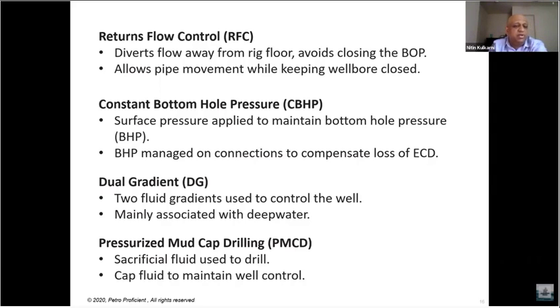In that case, you use sacrificial fluid in the well, which you continue to lose, and then you have a cap fluid in your annulus that you fill with, and then you manage your pressure by balancing the cap fluid and your sacrificial fluid that you continuously pump in the well without any returns to surface. But you manage your pressure in the well such that you don't get any kick from any other formations. So these are the 4 variants of MPD, and each one has its own application.